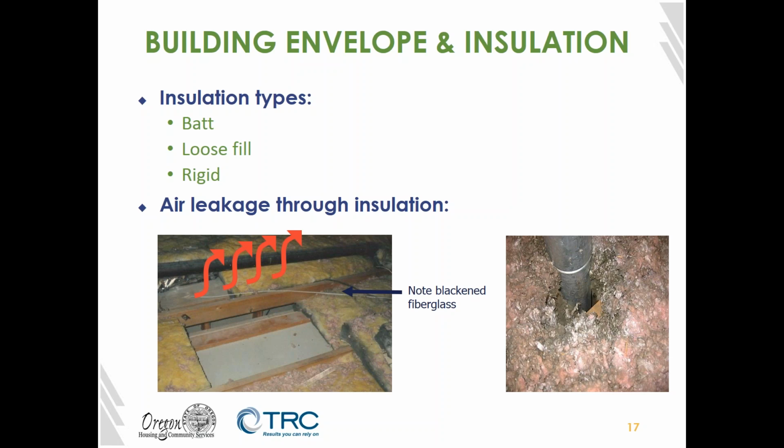Another thing that you have to keep in mind with insulation is when it's being installed, that's a really great opportunity to look into airflow through the building and air leakage. So while you're in the attic or wherever you're adding the insulation, they can go and seal up the cracks between boards and the gaps in penetrations, and that will prevent unconditioned air from coming into or leaving the building when you don't want it to, or from having air that is from an unsafe, non-quality controlled air source coming into the building.